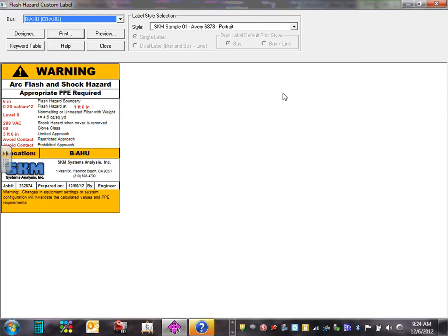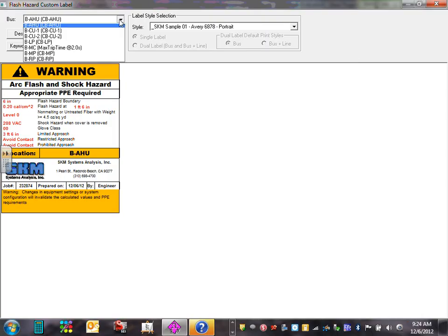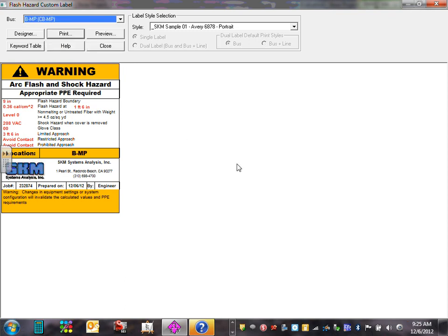Now, let's go look at the arc flash. After you did the arc flash, let's go to the main. Can you guys see at the beginning, anybody remember what it said at the main? It said you can't work on it. It's dangerous. Anybody know why you can work on it now? We put circuit breakers in and we adjusted them.